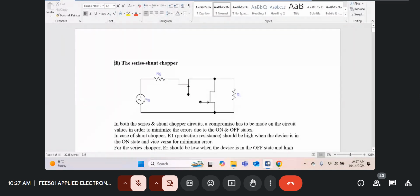And in that table, we computed the on and off errors for series and shunt choppers for various values of load, with generator resistance equal to 0, to check their performances. What is the on error? What is the off error for the series and shunt, so that we can make a decision as to which switching configuration we should use. And we found that in general, the series chopper was outperforming the shunt chopper in terms of the errors.